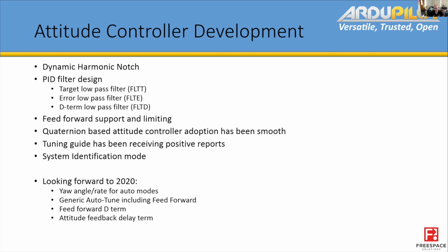At the moment, we hard code it for multi-rotors. And so we can't use it at all for tuning up helis, for example, because helis use feed forward in roll and pitch heavily, and they have a different filter and tuning methodology for yaw. So auto tune can't be applied to all three axes.